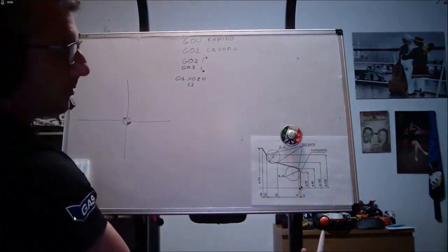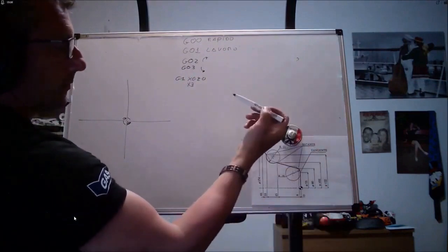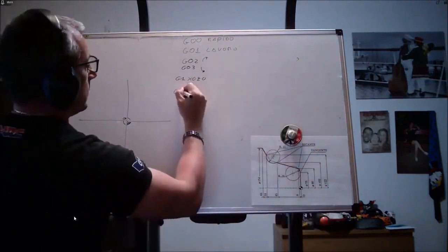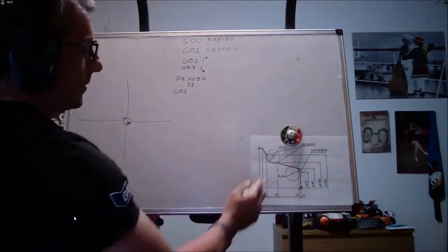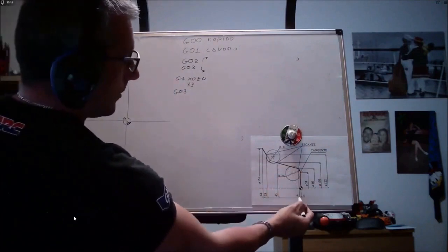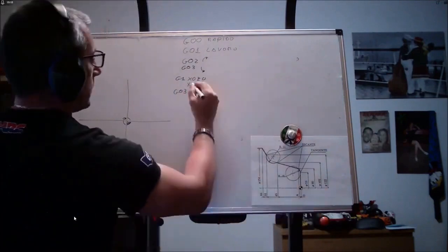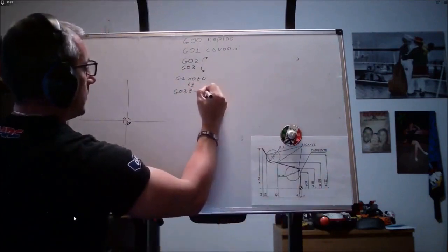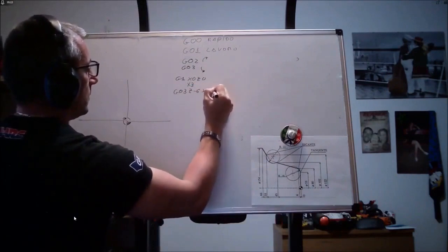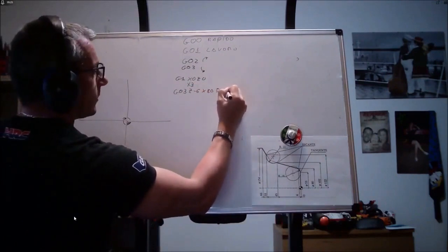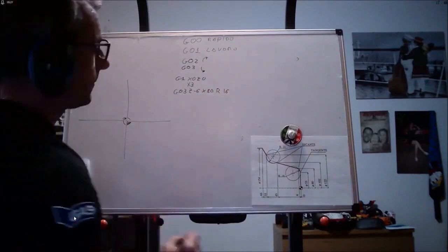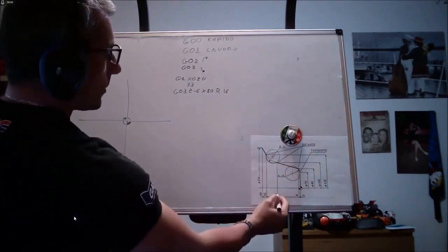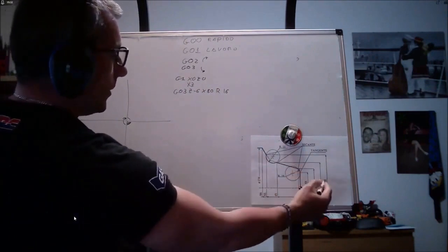Then we have a radius to traverse counterclockwise, G03, Z6, X80. And here we put our R16. Then we insert two coordinates that take us to Z45, X102.